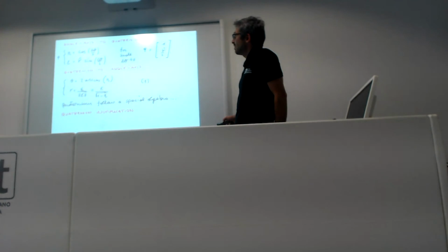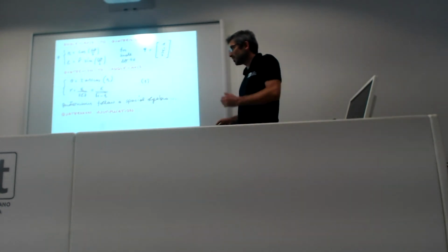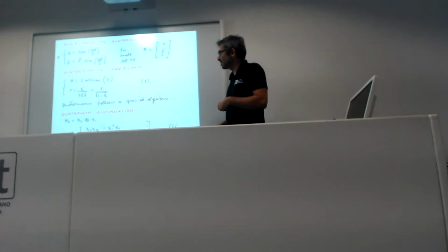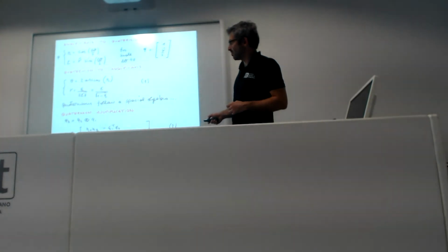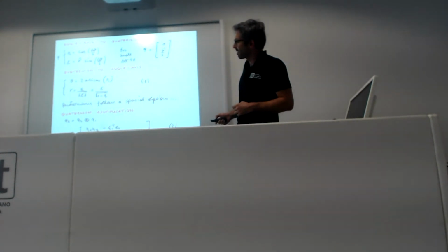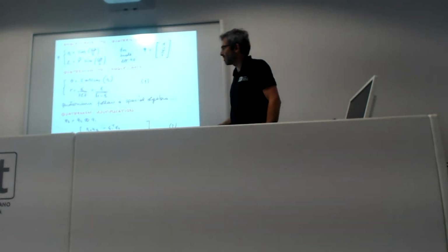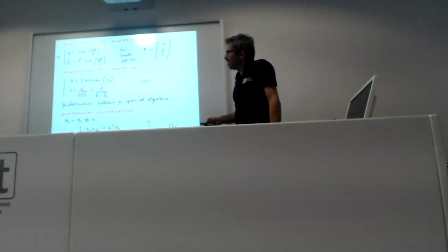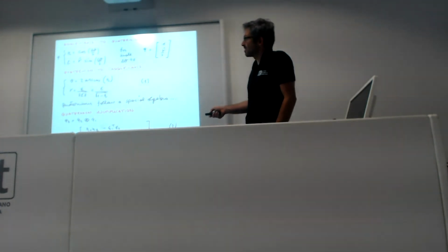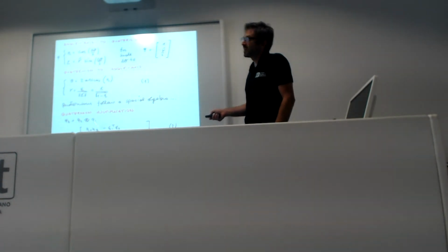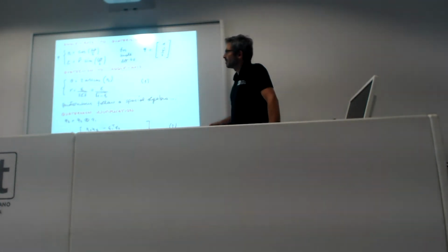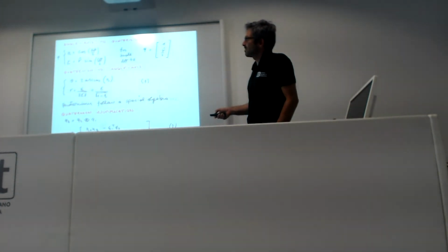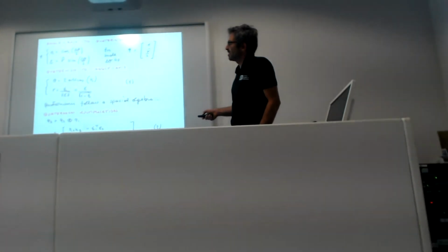The special thing about quaternions is that they follow a special algebra. There is a multiplication operator defined this way, with vectorial parts and some expression of the vectorial and the scalar part. To compose subsequent rotations, you just apply this multiplication to the quaternions relative to the rotations that you want to compose. So this is a rotation between A and B, and this is a rotation between B and C. Q3 is the rotation between A and C.